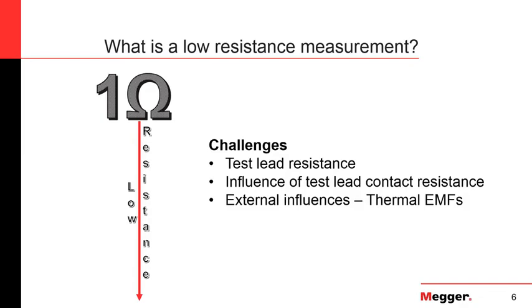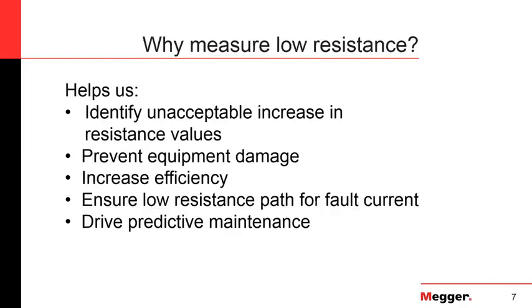So now that we know what a low resistance measurement is, you may be wondering, why should I measure this? If we recall from Ohm's law, we know that for a specified energy source operating at either AC or DC voltage, the amount of current drawn will depend upon the resistance of the circuit or component.